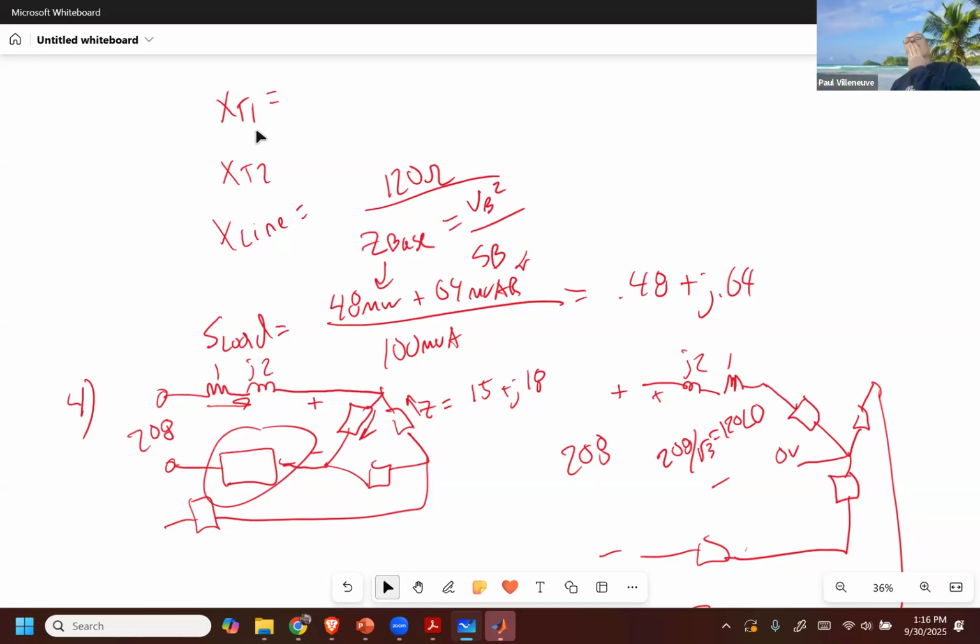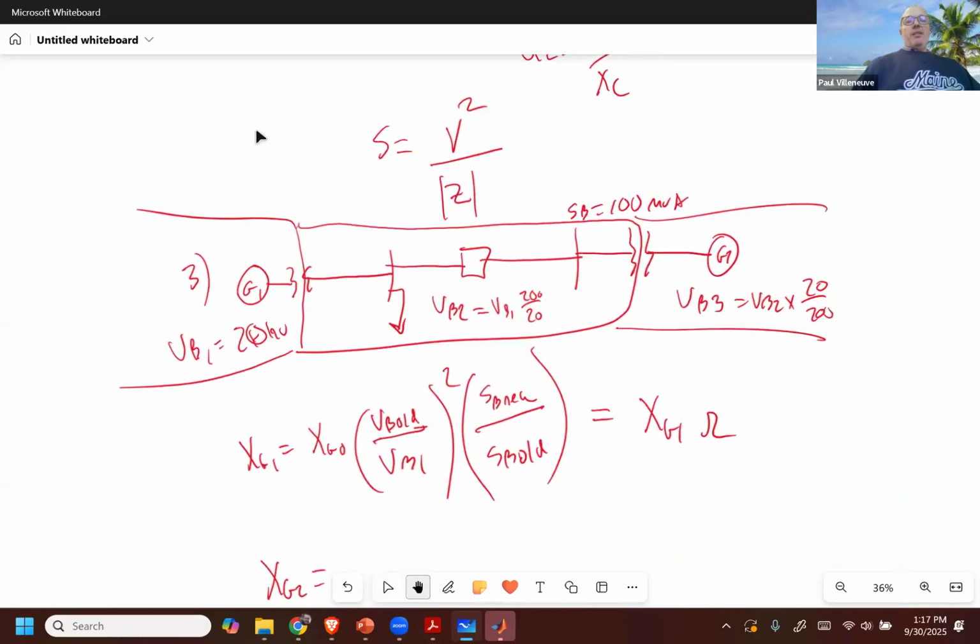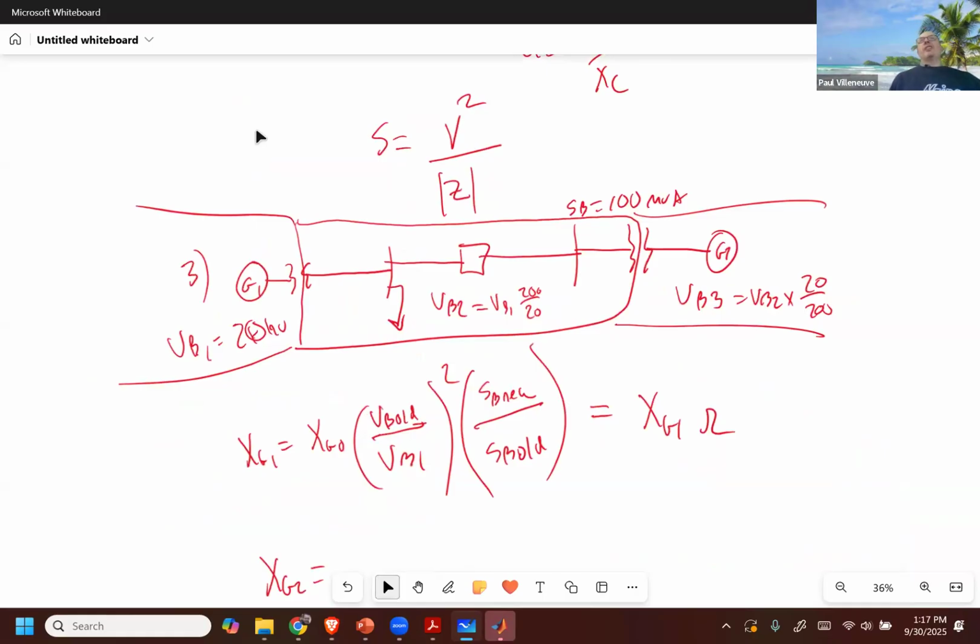Really quick on that, Nick. I guess what would our answer look like for that question? Not the numbers, but I would redraw the diagram without any of the transformers in it. Right? Because once you go to per unit, transformers are gone, so they don't exist. No, it's exactly like this, sans the transformers. Yeah, it's just a line with the line impedance all shown there.